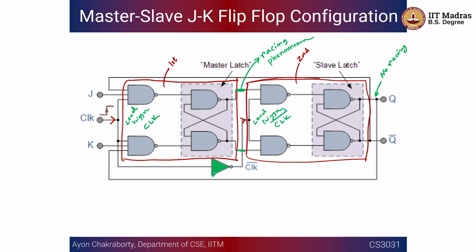So effectively what we are getting is you start avoiding that metastable condition in the final output Q. You are not going to have any race condition, and you can verify yourself that once this has passed, it is going to be locked. Okay, the output is not going to toggle for this infinite amount of time.